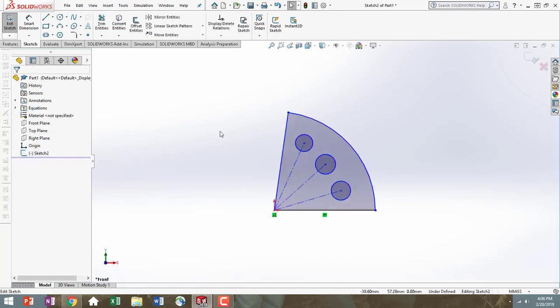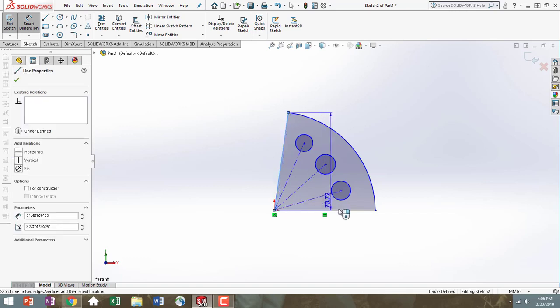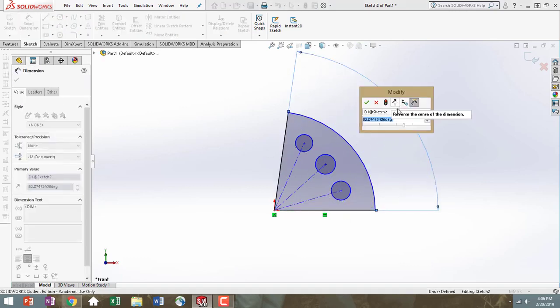I'm going to go ahead and open my sketch again. And now I'm going to start dimensioning this. So to begin with, I'm going to dimension my A1. So remember, we don't want the angle of just our arc to change. We want these line segments to be able to change. So I'm going to put my angle between both those line segments. I'm going to bring that out.